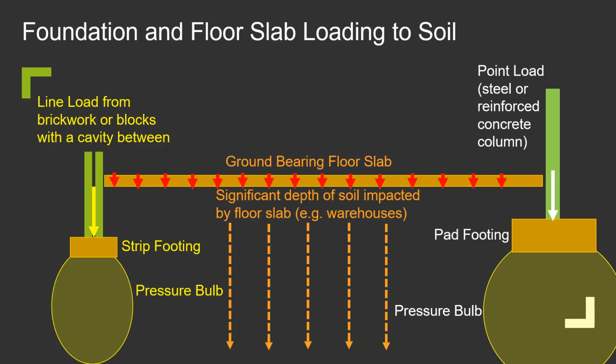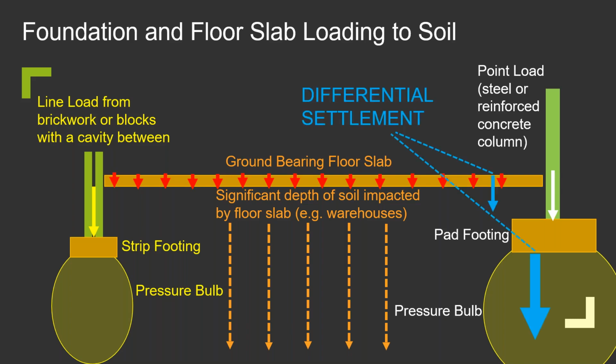Or we might look at ground improvements underneath where the floors are going to go. And it could well be that, due to assessment of the differential movement between what we think the foundations are going to move and what the floor slabs are predicted to move, if that differential is excessive, then we would use ground improvement to attempt to take out the settlement within that floor slab area.